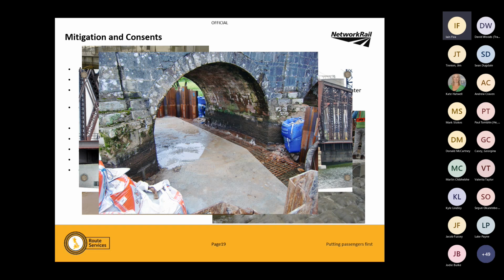There are quite a lot of fish-friendly pumps that you can get, where if you need to overpump a river, the fish don't get minced as they go through. There's all sorts of stuff that we can do. The hard invert that we saw at the Mill River one, where we've got the Welsh Water pipe, they're generally now frowned upon because they tend to cause more problems than they solve. They're trying to push us down soft engineering routes, which I'll come on to, but it's a strange one at the moment. They don't like us pouring concrete in a river. I don't know why.